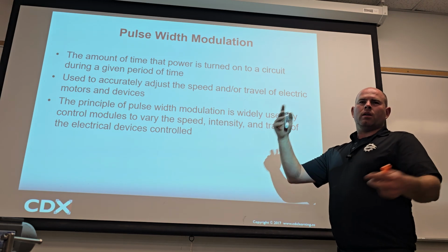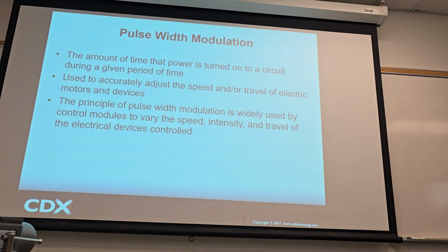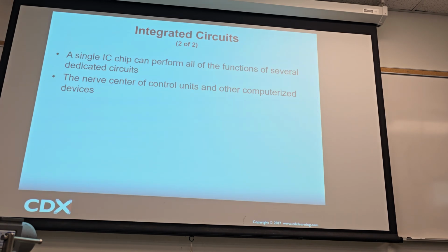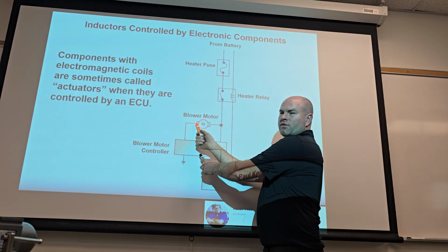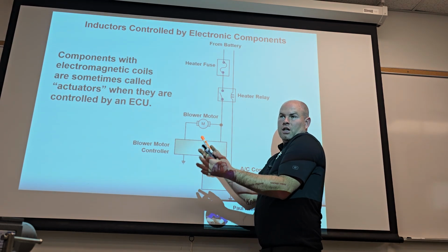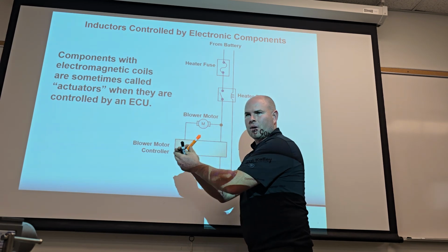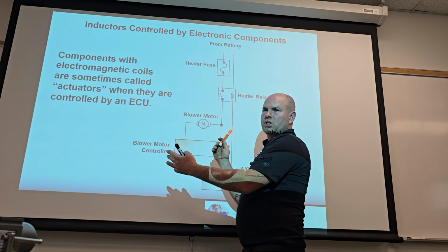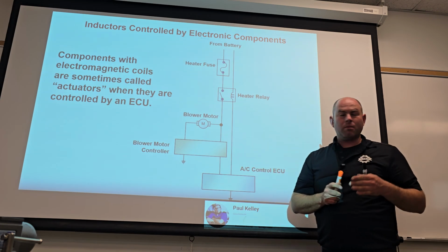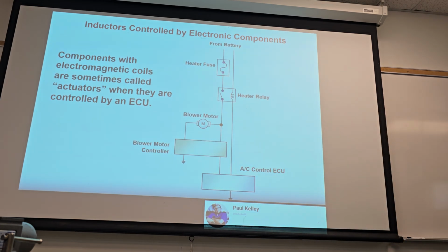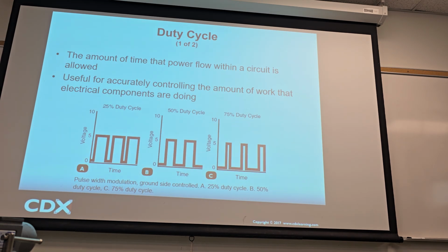But either way, the service manual would tell you, check that motor to see if it's getting the correct duty cycle or pulse width. So when we go to do that diagnosis, just understand, you're not just checking for 0 volts right here. You're checking for a specific pulse width, a specific milliseconds, or a specific percentage on the duty cycle, which your basic meters can't do. Some of the high-end meters can do, but you know what's really going to be the tool to check this? Oh, dang it. We're going to get more advanced. This is when we get into those oscilloscopes.